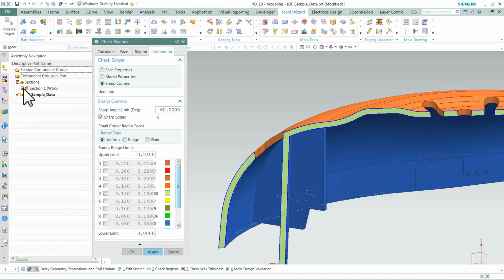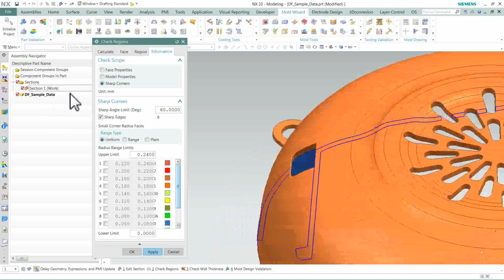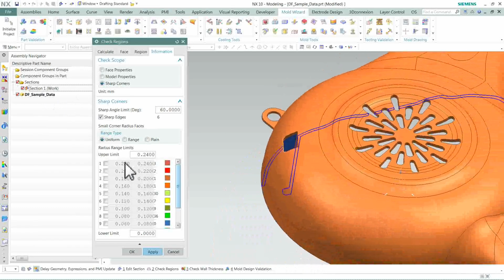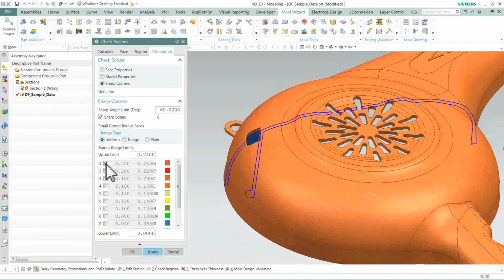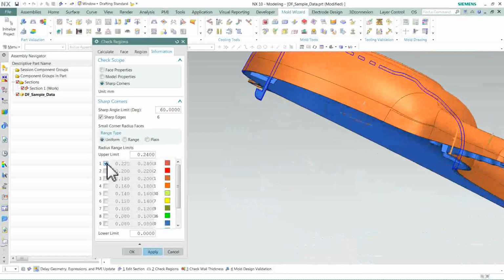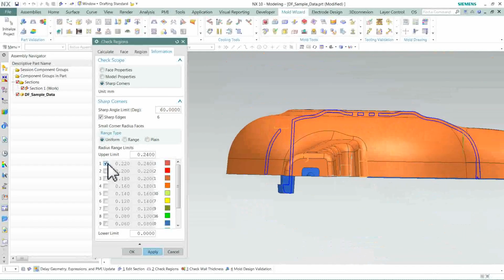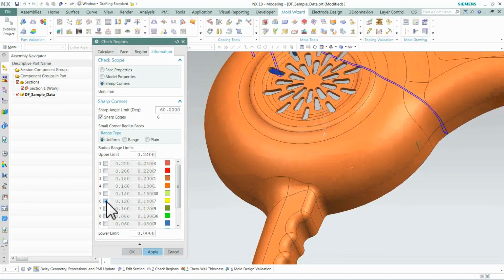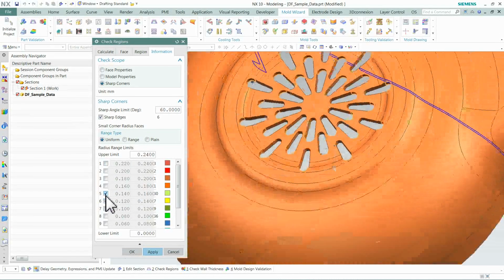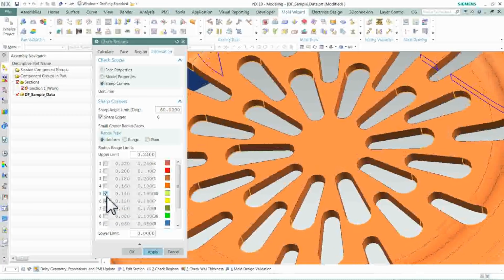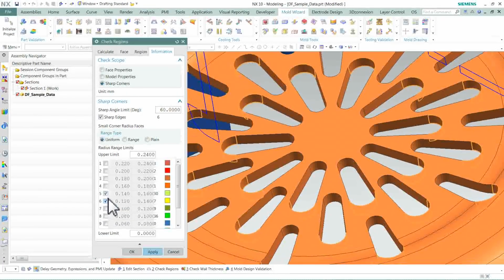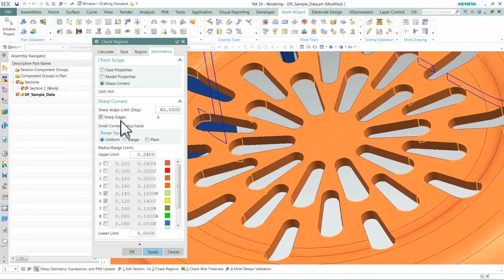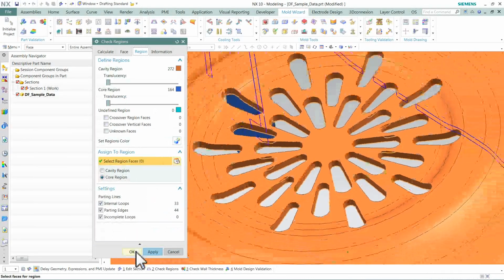We also have some other checks here, and here we're checking the minimum radii sizes. So you can see here with these radii that are showing up, because of the way they're going to be formed on the cavity, they're not really a machining issue. The space between the slots would be a bigger issue. With those tools, we can also use them to find the minimum radius of machining down inside a cavity, which we can get into later in a different episode.